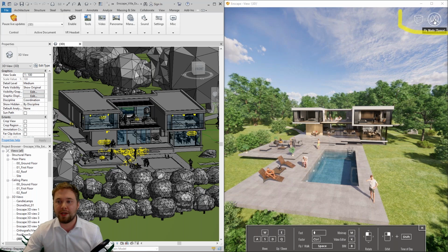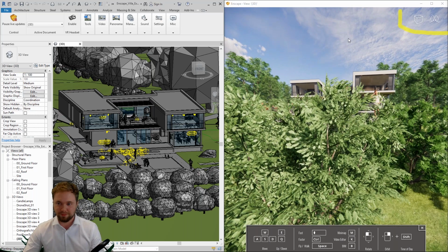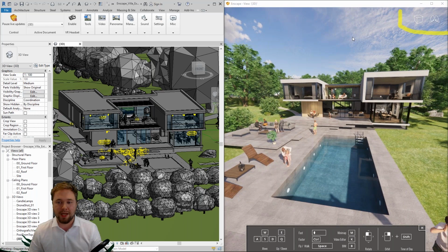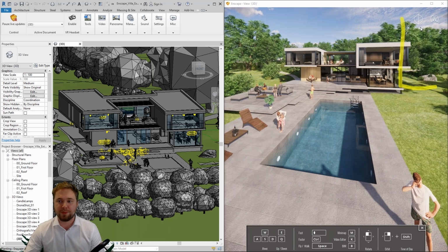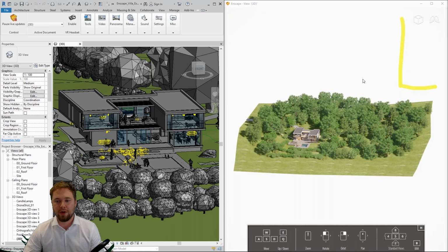One that decides whether you're in fly mode or walk mode. So you can also just control it by clicking this icon in the Enscape interface, but also, and more importantly, the perspective selector. Let me maybe mark it a little more clearly for you, so we should see it somewhere here. The perspective selector, which lets you decide regular perspective, two-point perspective, or the new orthographic perspective.